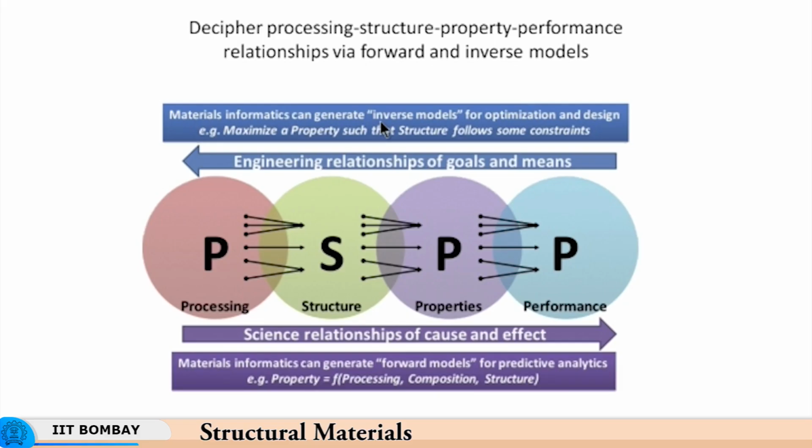The grain refiners might have been added. Whatever I might have done to get a fine grain size, these processing conditions or process parameters are listed out, and then correlated with the expected grain size. For instance, when we talked about melt spinning to get amorphous metals, we talked about a cooling rate. If I want the structure to have extremely fine grain or amorphous structure, then I will have another parameter called cooling rate.